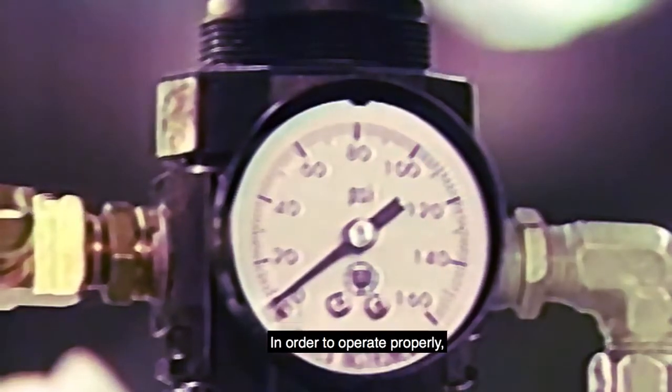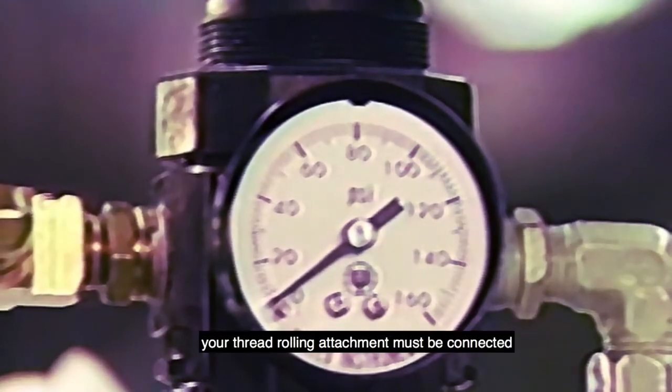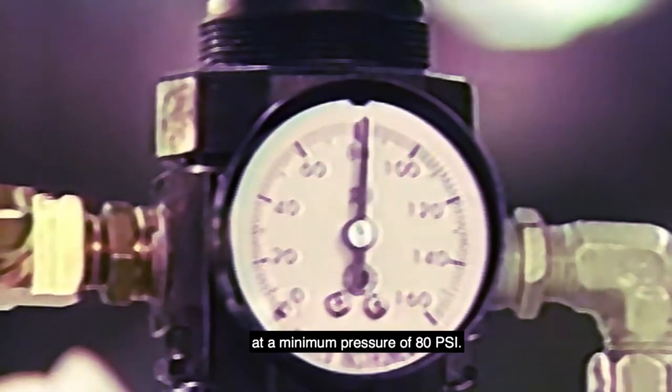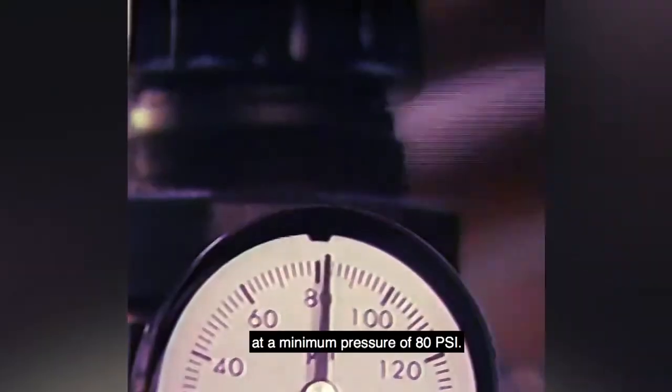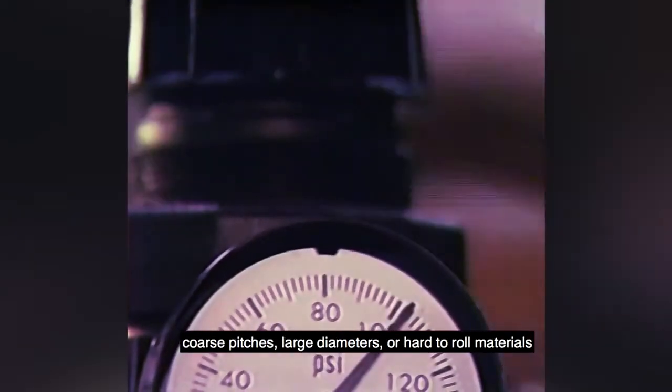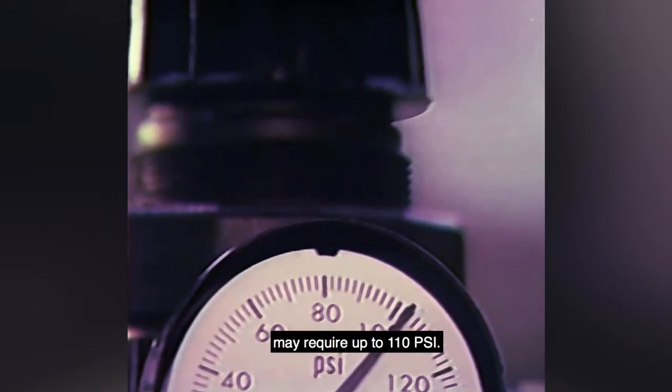In order to operate properly, your thread rolling attachment must be connected to a steady source of clean, dry air at a minimum pressure of 80 psi. Difficult applications involving long thread lengths, coarse pitches, large diameters, or hard-to-roll materials may require up to 110 psi.